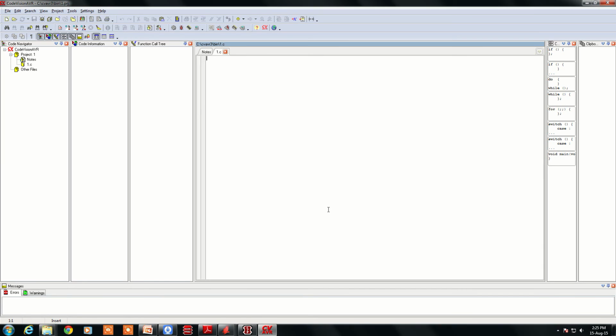Okay, now let us see how to write an embedded C program for the AVR microcontrollers. There are two softwares available. One is CodeVision AVR, the other is WinAVR, which is open source. We are starting with CodeVision AVR because it has some good features where even a beginner can write the program for the controller without knowing about the hardware initialization or the control words. That is, there is a feature called Code Wizard that we will see.